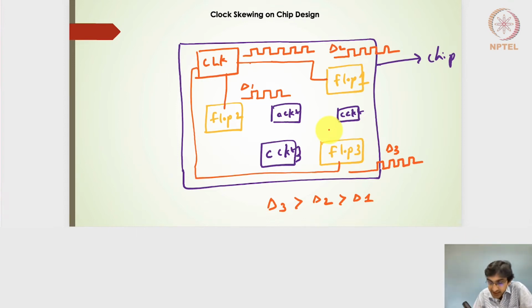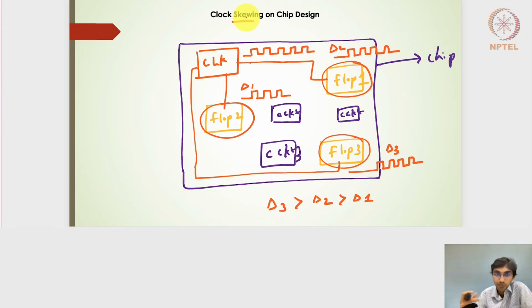And while I'm designing at a stage before placement and routing, what we really want to do is, irrespective of the flops' placement, ensure that even if I have a delayed clock, even if I have a skewed clock, the circuit should be able to capture the output. The sequential element designs, it could be a flop, a latch, or a pulse latch, should be able to capture the input at that particular skewed clock.